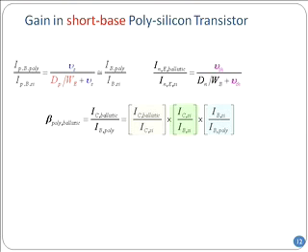So I could compare how the ballistic collector current compares, I_C ballistic divided by I_C silicon when it's not ballistic. Then I can see how the collector silicon, normal standard, the green part, how it relates to the base current, you know, the classical one.